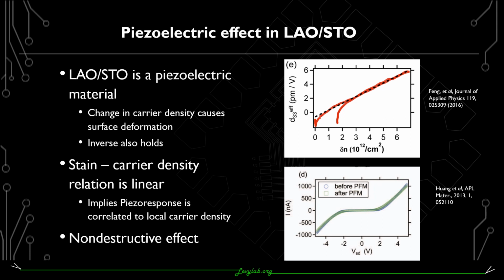true. And so from this, we have shown several interesting properties. Specifically, we have shown that the piezoelectric strain tensor can be directly correlated to the local carrier density under certain regimes. Moreover, we have shown that this effect is non-destructive, and I'll get into later why we care about that so much, by taking IV curves from before and after running PFM and seeing that they're the same, indicating that the structure is essentially unchanged from this